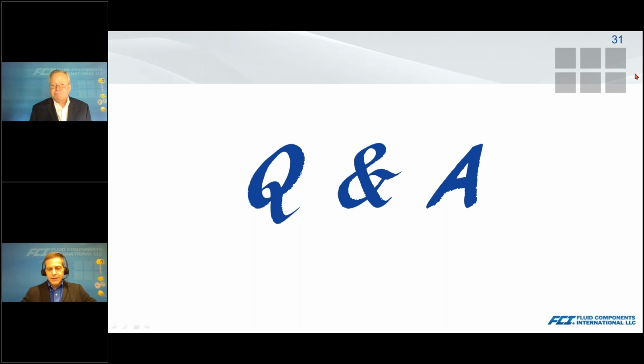That's a good question. Again, ideally we're looking for these fully developed flow profiles. Our experience has always been 20 diameters upstream, 10 diameters downstream without any obstructions. It allows for that fully developed flow profile, whether it be turbulent or laminar. You start shortening that distance and you're having an impact on your accuracy, and it can change greatly depending upon what's upstream of the metering point as well as downstream. So you really need to take into account all those conditions.